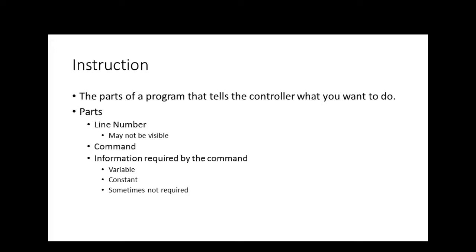And the first commands we're going to look at are going to be move commands. Now there's a lot of commands in the robot. But what we're going to do first of all is just learn how to make the dang robot move. Now we know about jogging, but jogging is not programming, right? You understand? If I had to have a person out there with that teach pendant moving that robot around and telling it to open and close or move around, then I might as well have a person doing the job. In fact, the robot will probably be slower, right? You'll understand that. So the commands we're going to start out with are what we refer to as move instructions.